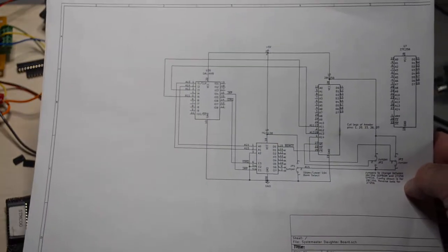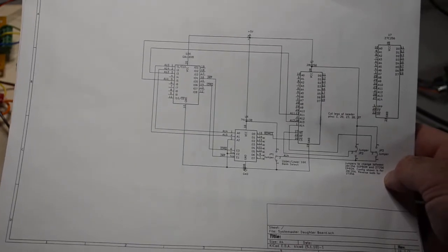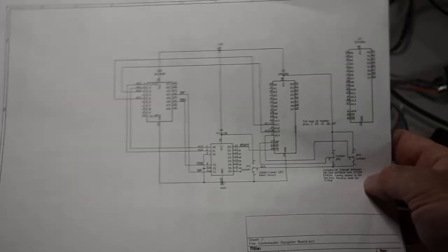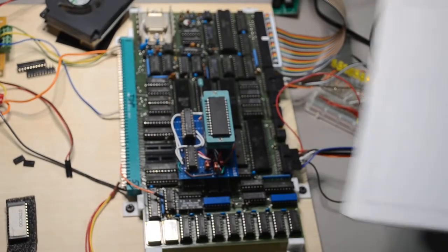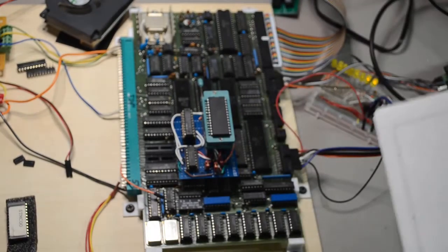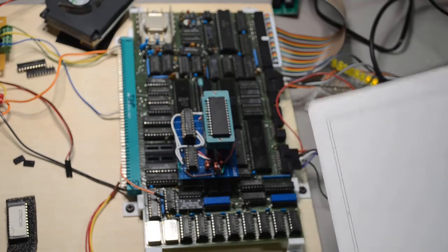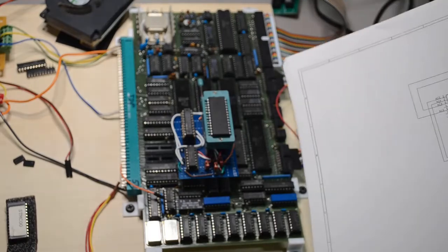Suddenly I've got 16K of EEPROM, where before I only had 2K. Perfect, right? Well, not exactly. Like I said, the board isn't really designed to address more than 8K. And that's only if I make the changes to the jumpers and the bodge wires. So it's kind of stuck in 2K mode.